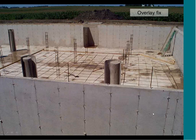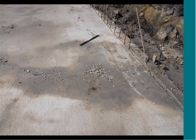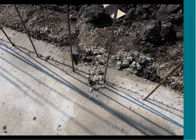That's a good one. And you can see all of these wet areas here that look like they haven't cured yet. That's just mud mixed in with the concrete that has kept it from curing properly. And you can see this is the forming that is happening to do a 3-inch overlay. Some more mudballs. Mudballs by the keyway.